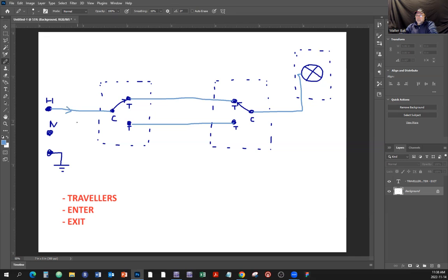Okay, so actually I'm just going to draw an arrow. Okay, so let's see if we have the closed circuit. We leave hot, we go to the switch. Oh, this is connected here. Okay, well, we can travel through the traveler conductor. Oh, we got a connection, we can go into the light bulb. Whoop, that's it. No more pathway. There is no connection between this and neutral. Well, you know what? Let's connect it.